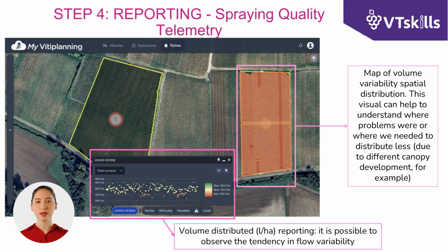Among the outputs that can be obtained from telemetry systems are digital raster-type data, in which it is possible to see the liters per hectare dispensed by the machine and acquired by the sprayer's flow sensor. This provides an overview and specific details of the spatial distribution of spraying. This makes it possible to highlight where anomalies have been recorded and to study the causes that led to them. These causes may be due to anthropic factors or related problems, such as unforeseen events such as elements hindering progress. The data displayed allows instant analysis and corrections to be implemented.